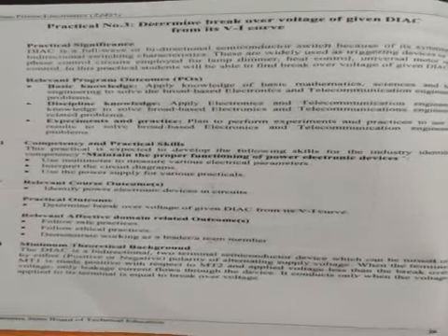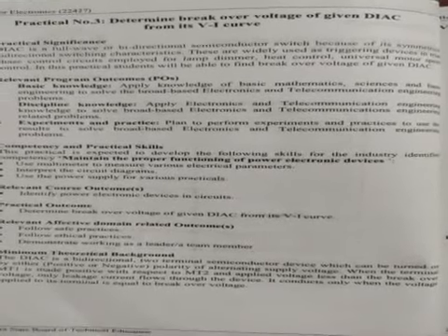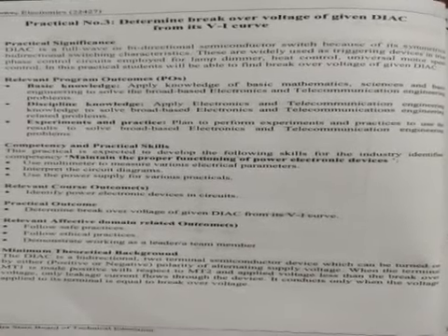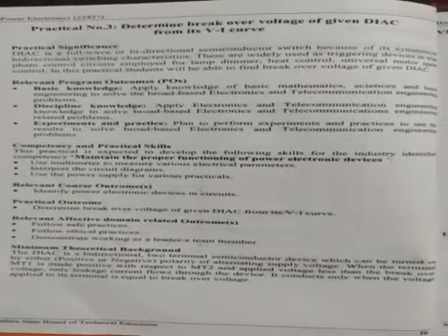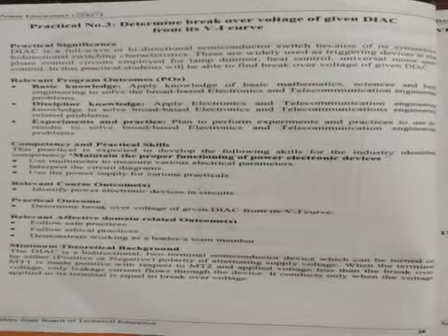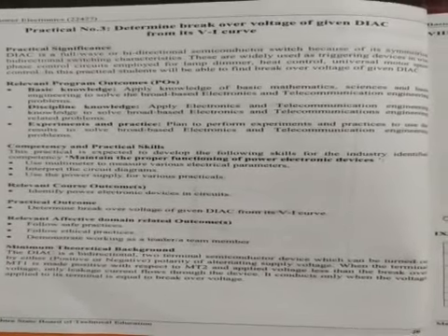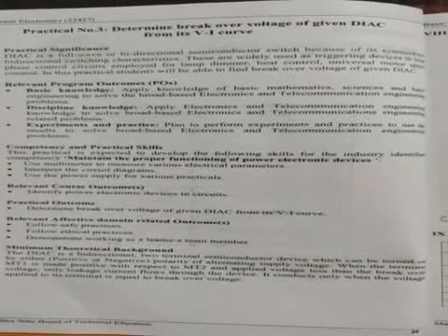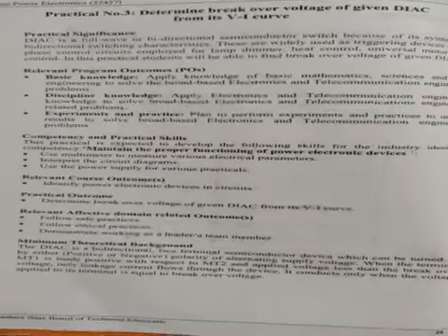Because of its symmetrical bidirectional switching characteristics, these are widely used in triggering devices in the triac phase control circuits employed for lamp dimmer, heat control, universal motor speed control. In this practical, student will be able to find the breakover voltage of the Diac.